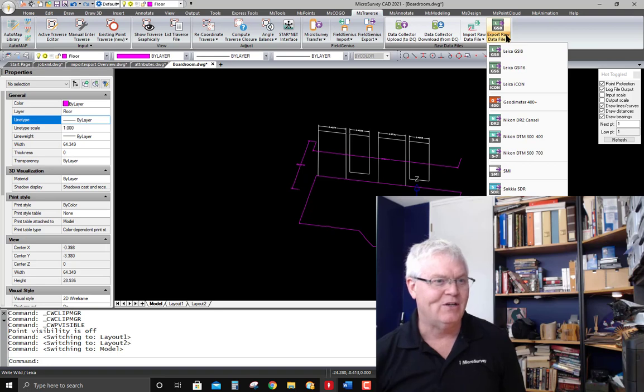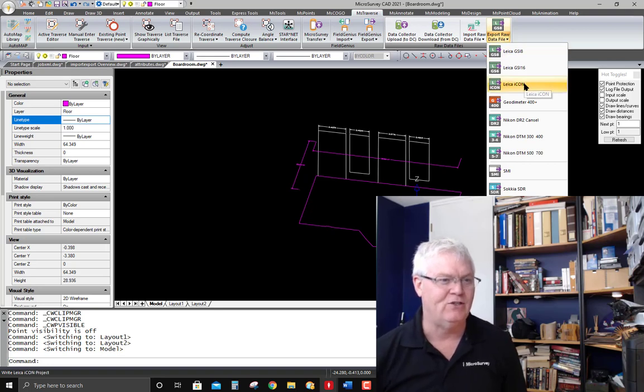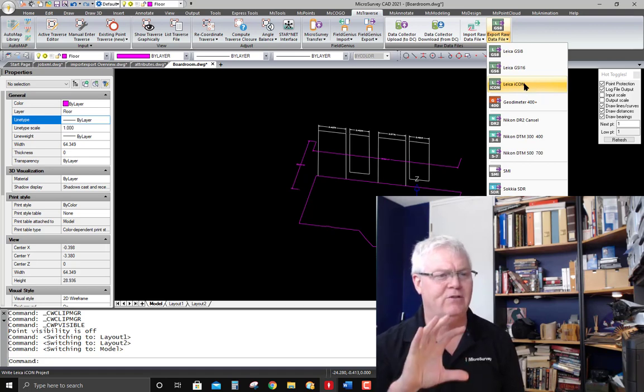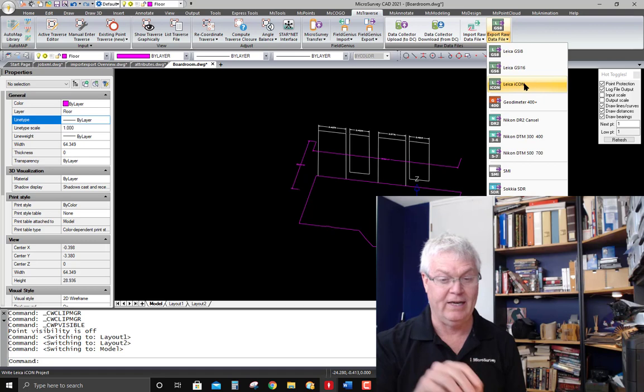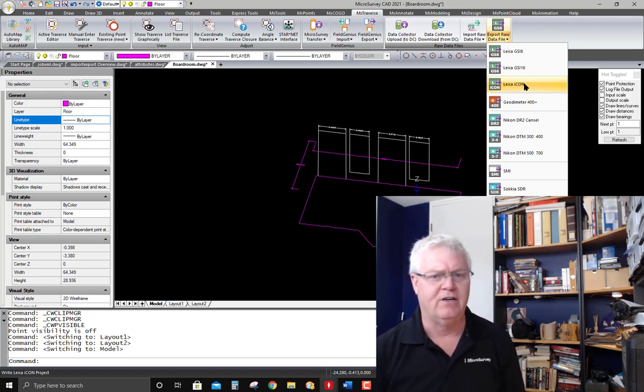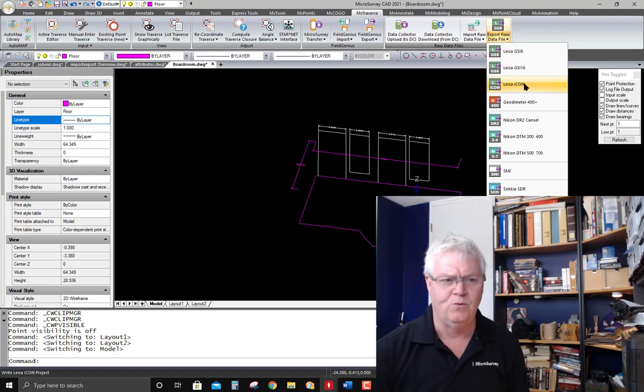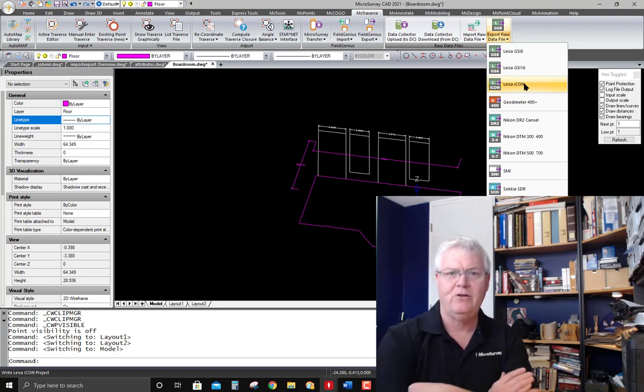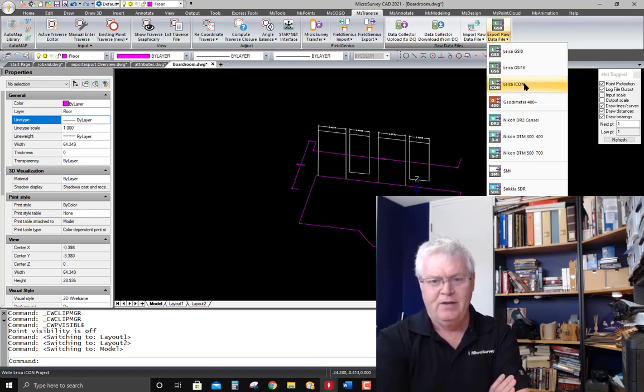And one of the ones that I like to bring up these days is this Leica icon export. It works much like the FieldGenius one. It allows you to window in an area in your drawing, and it automatically generates a DXF file and an ASCII file that's very easy to import into not just Leica icon, but lots of different formats.